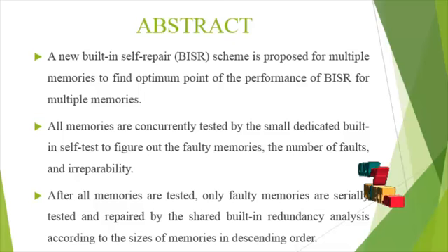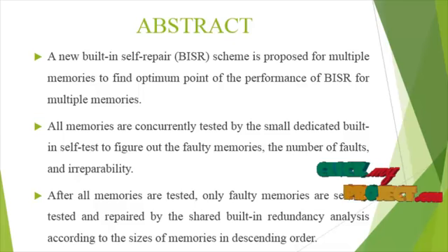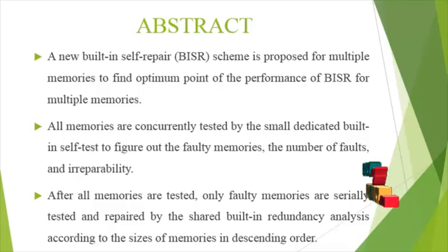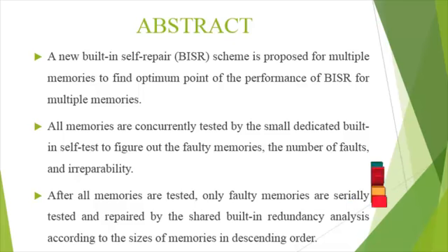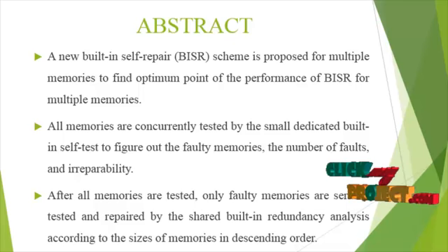Today's chips and background technologies allow the implementation of multiple memories on a single chip. Due to their high density, memories are more prone to faults. These faults impact the total chip yield. One way to solve this problem is to enhance the memory by redundant memory locations. The address mapping of the fault-free working memory is programmable within certain limits.